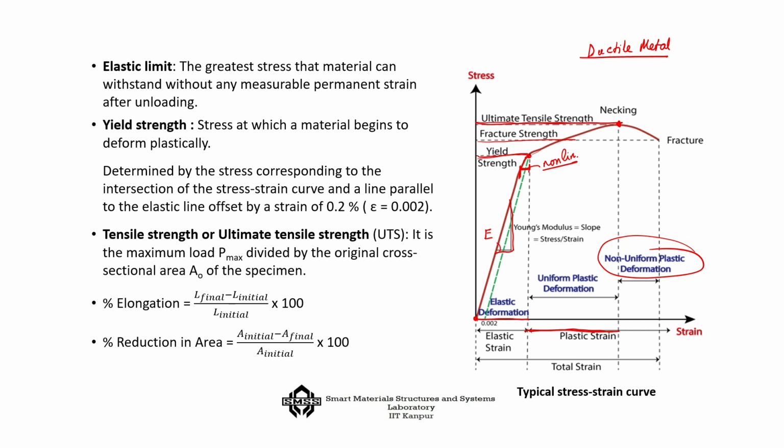Okay. So, all these things you are going to get, and also keep in mind that this is a typical stress strain diagram, which may also be called an engineering stress strain diagram, but there is a true stress strain diagram where this sort of decreasing would not happen. Okay. So, you will see that it is actually calculated on the basis of the actual area of deformation. So, that we will look into very soon.